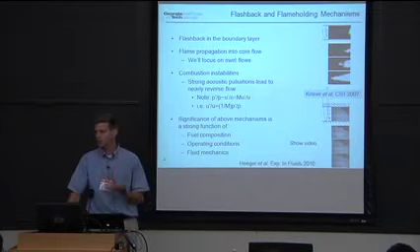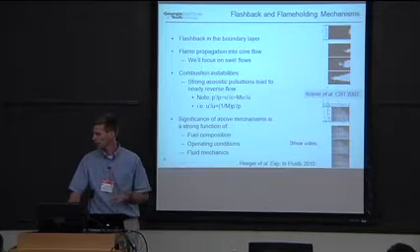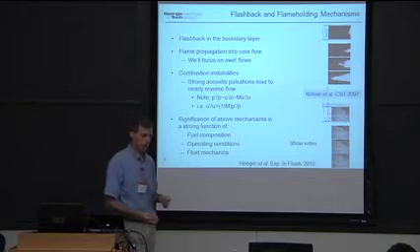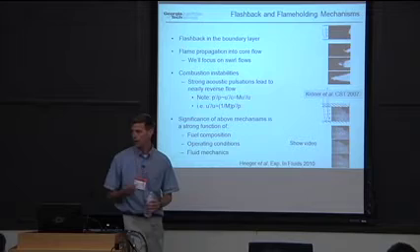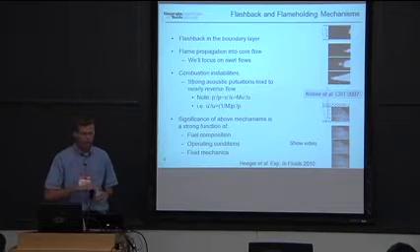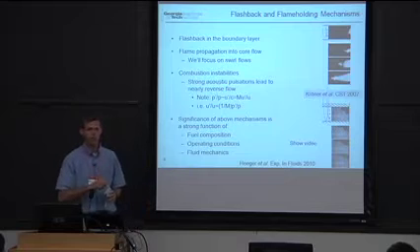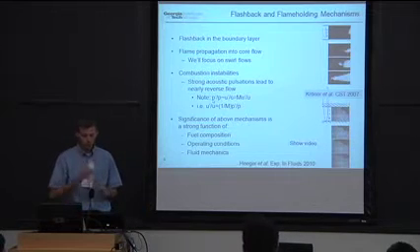It turns out, in fact, that oftentimes when you have very severe combustion instabilities, the reason they cause the most damage is because they cause flashback. Combustion instabilities cause long-term damage through fatigue, but they can cause very catastrophic damage in a matter of seconds by inducing flashback. I'm not going to talk about this mechanism here because I'm going to focus my discussion on instabilities tomorrow.